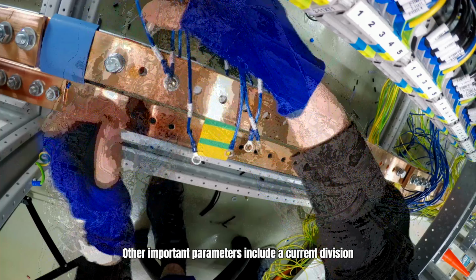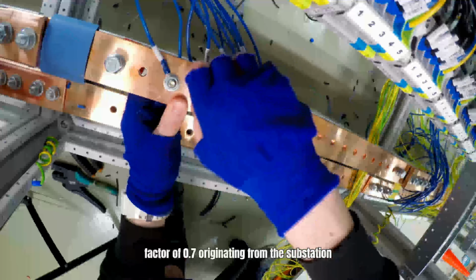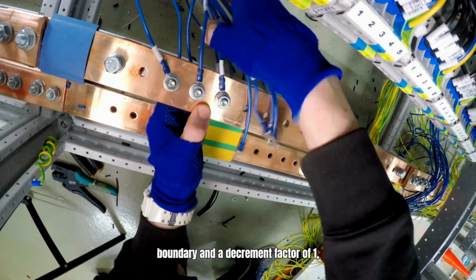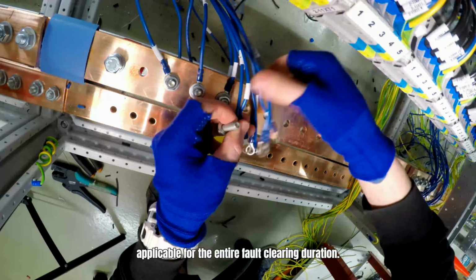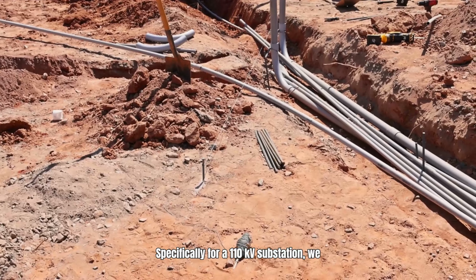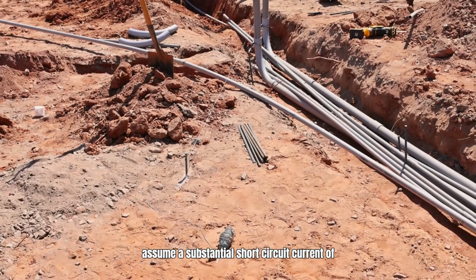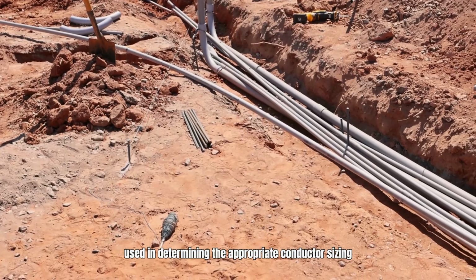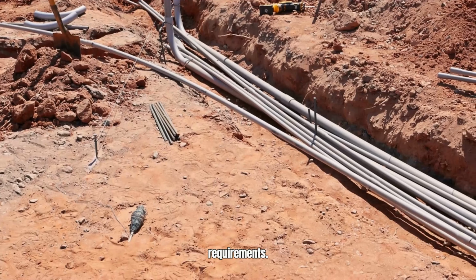Other important parameters include a current division factor of 0.7 originating from the substation boundary and a decrement factor of 1, applicable for the entire fault clearing duration. Specifically for a 110 kV substation, we assume a substantial short-circuit current of 40 kA, which is a key value used in determining the appropriate conductor sizing requirements.